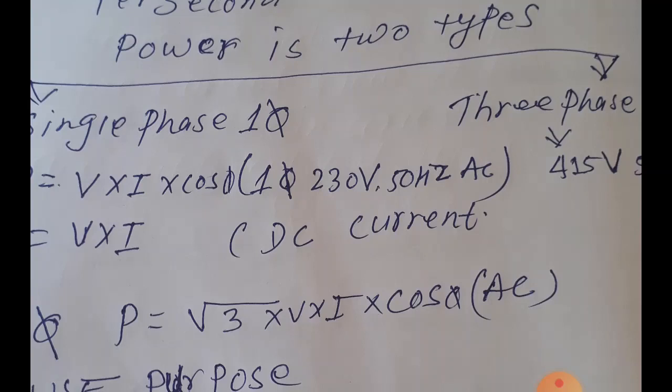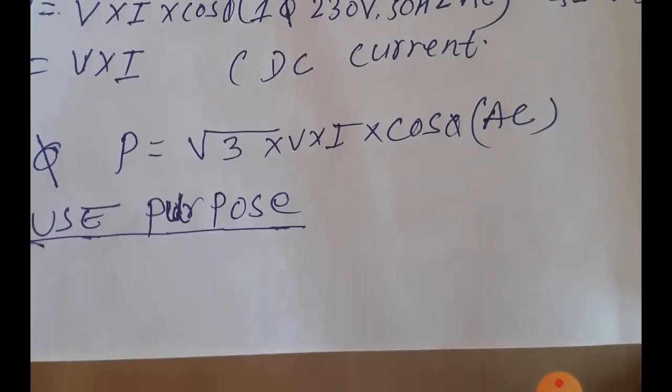So this is the formula for power and how to convert. If your equipment gives how many amperes it takes as load and how many volts, for single phase and three phase, you can calculate the power or amperes needed like that. Okay, this is your calculation.